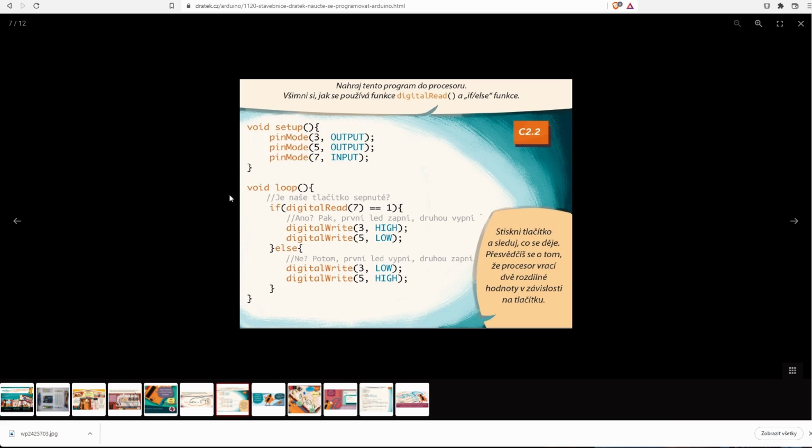By the way, this is a typical code in Arduinos, so in the setup function, and I will go into much more detail in a separate video. You set the pin modes, so you either read some voltage via input pins, or you output something to a different circuit board via output pins. And yeah, I will go through this stuff, so don't be worried.